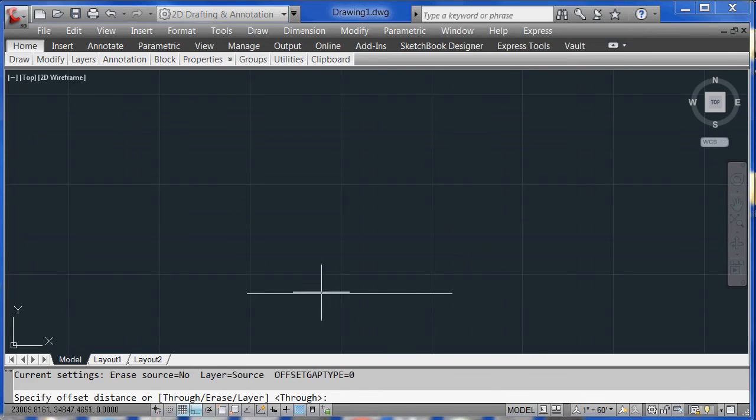So if you type O for offset, and if we look at figure 6, the little drawing we're supposed to draw, its width is 1, 2, let's see, I think we were 1, 2, 3, 3.5 units over. So if I type offset O, it's asking me how many units over. So I say 3.5, and I click the thing that I want to offset, and then I have to tell it which direction. So I say go that way. Okay, I'm going to zoom in here.